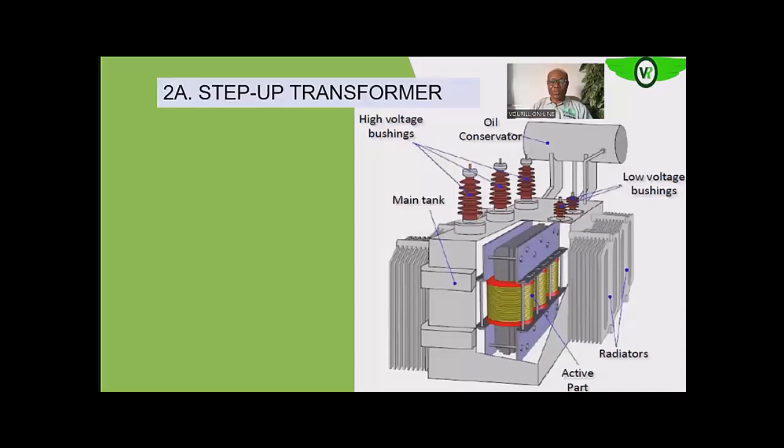In the course of operations, because of the effect of I squared R, power losses are bound to occur around the windings of the transformer. And these power losses, definitely, will come in the form of heat. So those heats, we need to take them out of the transformer. And that is where the transformer oil comes in. The transformer oil, apart from cooling the windings, also helps in insulating the active part from the inactive part of the transformer.